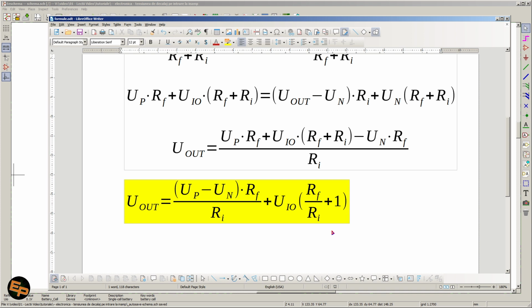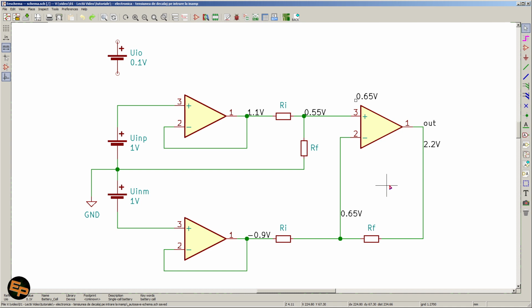And at an amplification factor of 1000, that's certainly going to be significant, especially since if we choose high amplification factors, it means that we have small voltages on the input, right? Small differential voltages, and therefore those input voltages will be basically comparable to this error voltage, this input offset voltage, which is an error for us. So it's very easy for us to have wrong results in such a case.